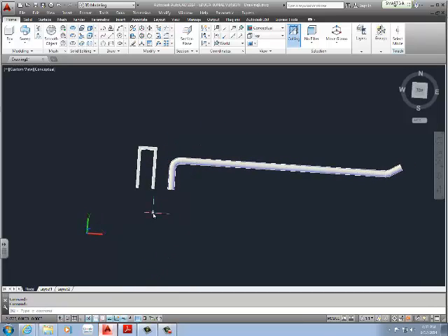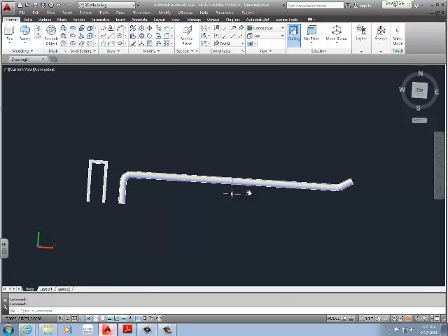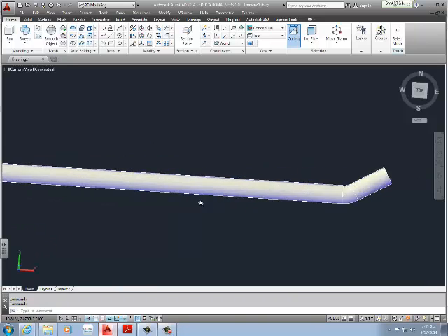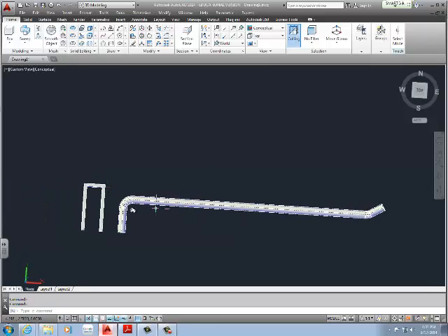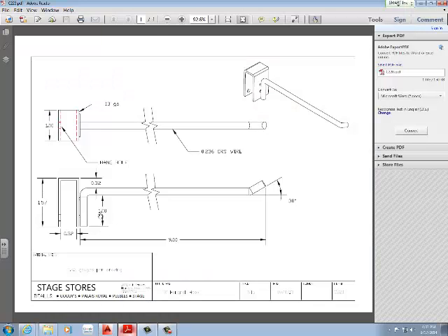There are actually 2 additional parts that we need to create for this drawing, and we also need to add a fillet to this edge here. Looking into the PDF, there's a hole over here that allows it to hang on for powder coating, and there are 2 projections, probably 0.04 wide, to allow for press welding. So the current, when they're welding it together, goes through that little gap, and that's what melts and bonds both these objects together.